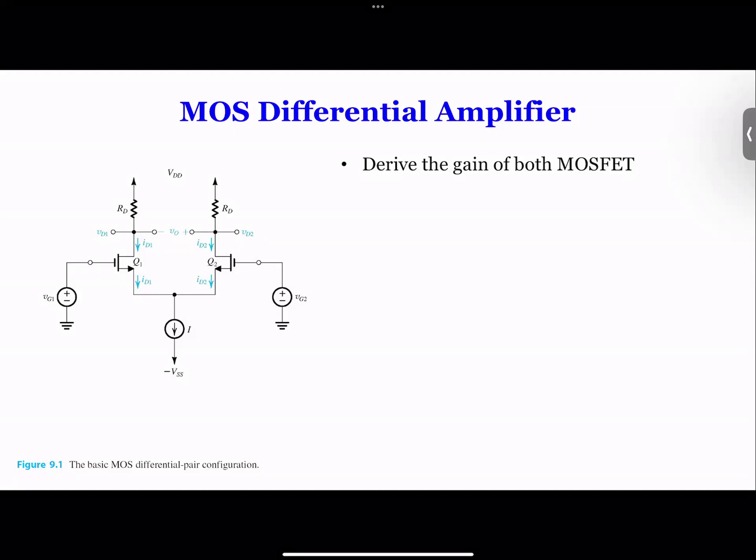So this is a differential amplifier. And some people look at it and say, oh, this truly looks like a current mirror. Does it? Not really. Well, there are a couple of differences, right? In the current mirror, usually you have the base to base, back to back. But this is not back to back, but head to head, right? Secondly, in the current mirror, you have the gates connected. But in this one, apparently the gates are not connected. They're connected to something else. They're not connected together. So this is not a current mirror.